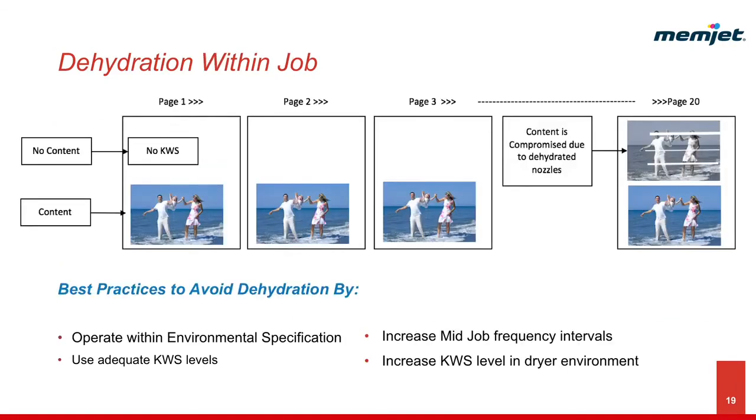The visual symptoms for dehydration within a job are the same as what we've previously viewed. There are two common use cases sensitive to this. Dehydration occurs within a job when the content changes and fires nozzles that previously were non-fired, as you see in this example. Another common use case that lends to dehydration within a job can occur with low content printing and inadequate keep wet settings. The mechanism in both of these cases are the same.